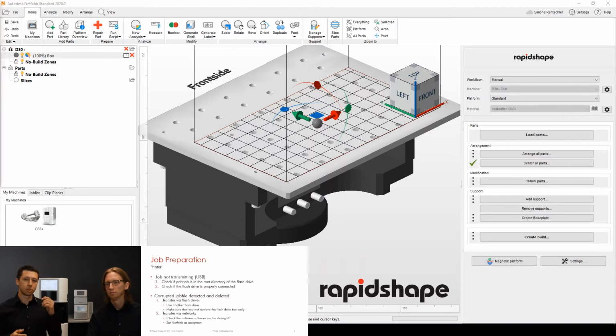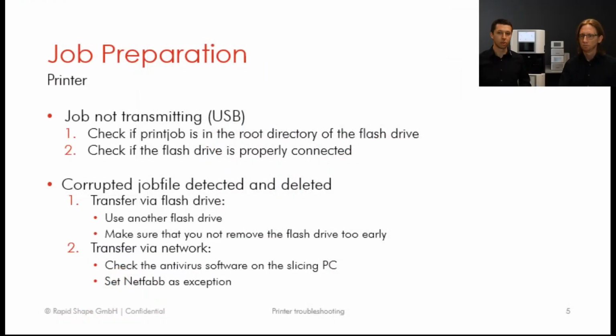If not, it's important that you check if the file is in the root directory of the USB stick. Otherwise it won't be copied from the USB stick to the machine, and it won't be found by the machine. The other thing is maybe the flash drive is not properly connected. That's also sometimes a reason for this. So these are the two main reasons.